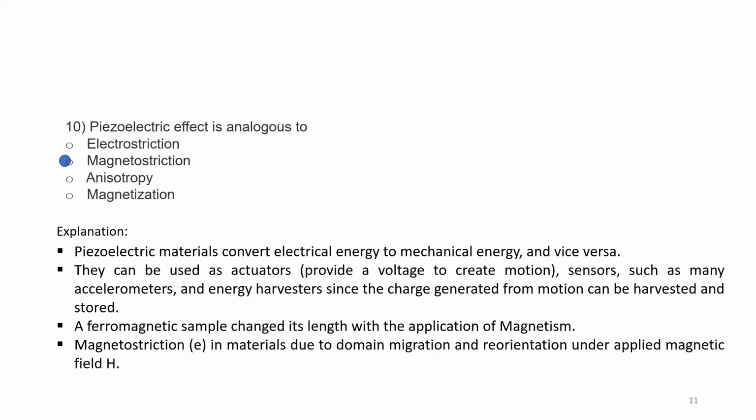Next question is, piezoelectric effect is analogous to. Your options are electrostriction, magnetostriction, anisotropy and magnetization. So the correct answer will be magnetostriction. Piezoelectric materials convert electric energy to mechanical energy and vice versa. In case of magnetostriction, if you apply a magnetic field, the domains will align in one direction, leading to a length change. It will also lead to a change in strain energy. That's why it is similar to piezoelectric behavior.